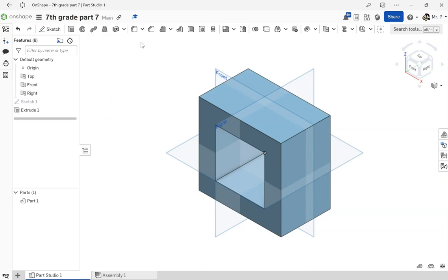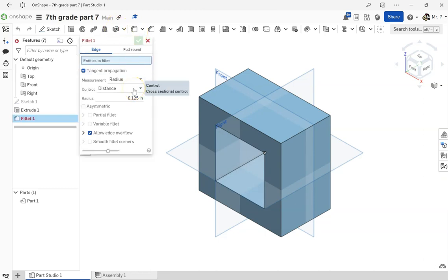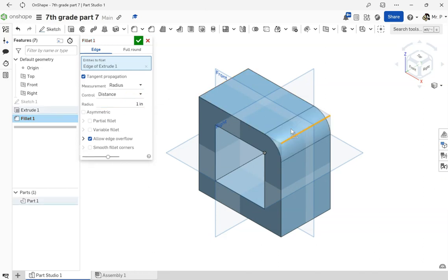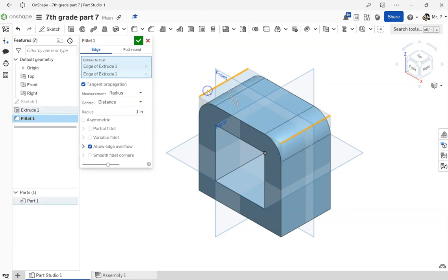There are going to be 2 fillets you actually end up using on this. I'm going to go with the big one first. The first fillet will end up being a radius of 1 inch. So I changed the radius first. Please always change the radius first. The reason for that is if you change it last, it may not actually show up. Sometimes it can show an error.